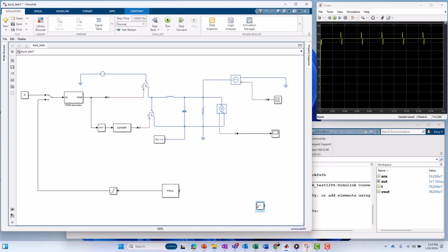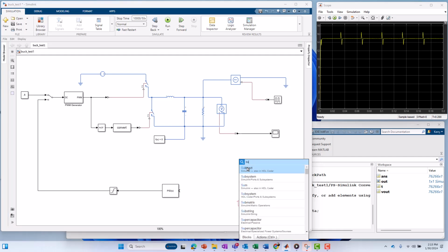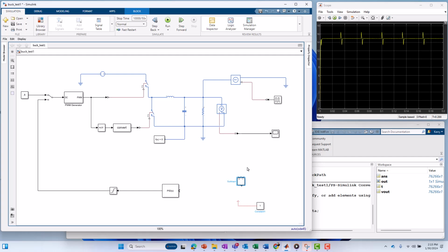Serve as our reference. Do the familiar Control R to rotate it. Move the label from top to bottom. That will feed into a subtract block. We'll reorient the subtract block likewise, move the label down. And now, here's another little detail here.